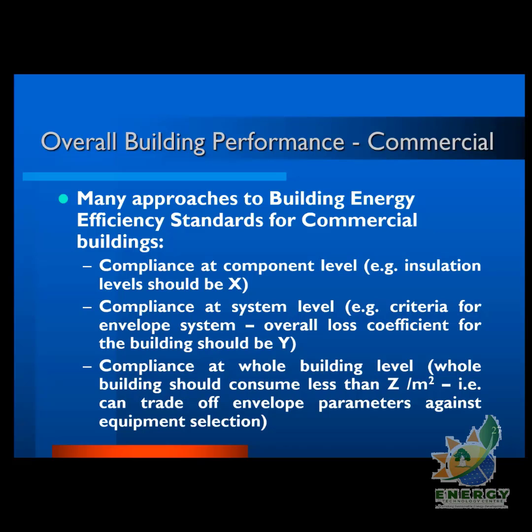Now, buildings of the same type, which perform the same functions, should consume an amount of energy that is comparable in terms of the specific energy use parameter. And this system level compliance can be used to differentiate between the energy performance of buildings.